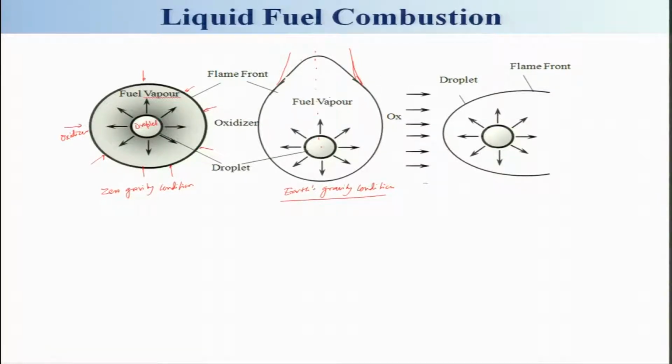Now the buoyancy effect also has to be taken care of. And there is another situation which is a practical one, where the flow will be there, or I can say this is the oxidizer velocity which is moving, and then I will get a flame here, and this is your wake region, and this is the boundary of the flame. There will be a boundary layer, hydrodynamic and also thermal. So this is also quite complex in nature.